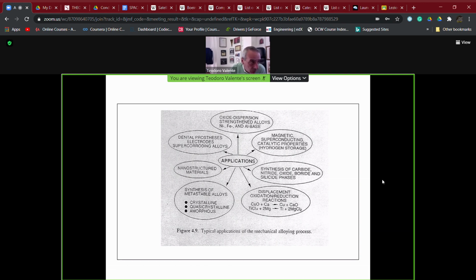But please remember that we are introducing, in terms of fabrication technology, an intermediate step, in the sense that we are going, first of all, to fabricate this kind of materials in powder form, by MM or by MA, mechanical milling or mechanical alloying, and then we need to use a consolidation technology, which is usually inside the area of the powder metallurgy technologies, on which we will say something more concrete later on.